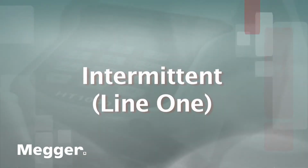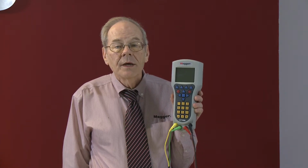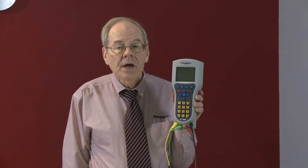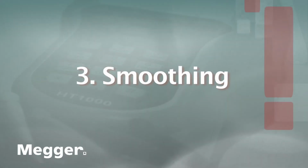Intermittent, line 1, identifies the intermittent events that are not steady but rather occur at irregular intervals. Line 1 should be connected to the black and red test leads. Intermittent, line 2, identifies the intermittent events that are not steady but rather occur at irregular intervals. Line 2 should be connected to the yellow and green test leads.